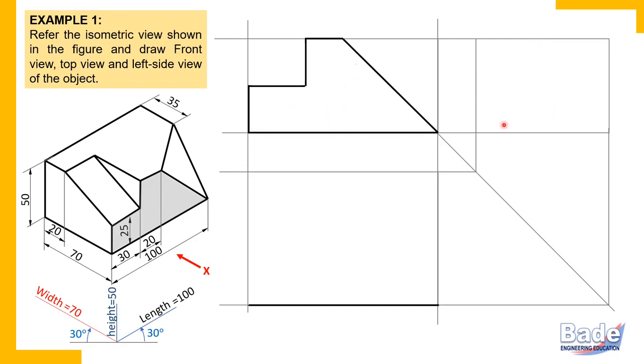This surface appears as a line on the front. Now remember, the line view of this surface must be in between projectors. So the highest point on the surface and the lowest point on the surface, that is the entire height of the surface, you are going to project it here. And that is why from top end and from bottom end visualize projectors, and you will get that line on the front. So this surface is over in front view, top view and side view.